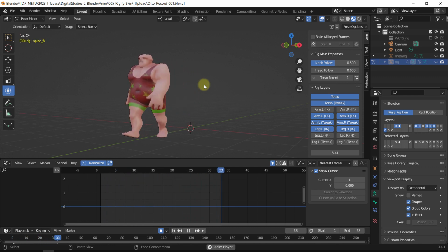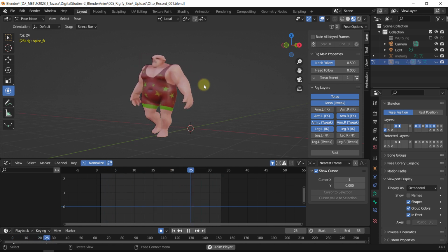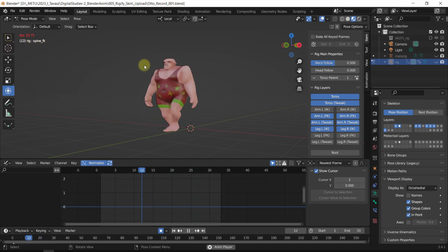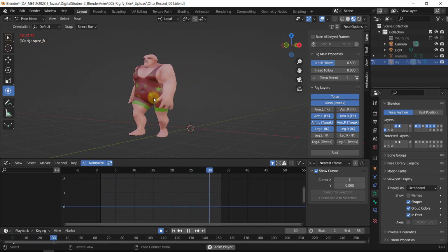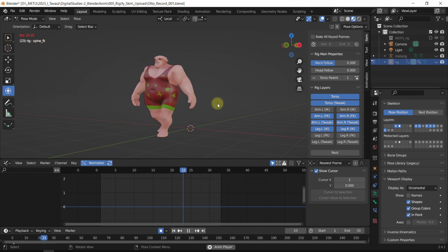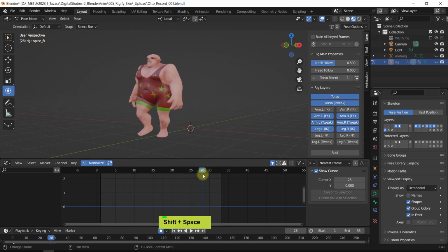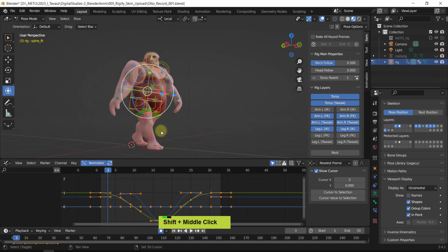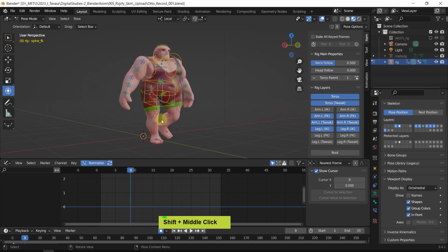All right, so basically that is a simple walk with various adjustments to make. So regarding the arm movement, the shoulder movement, the head positioning, and as well the legs, and also the other parts around the hips, you can fine-tune so many things. If you want to make it more character specific, the biggest change you can make is to save your file and focus mostly on changing up the passing poses.